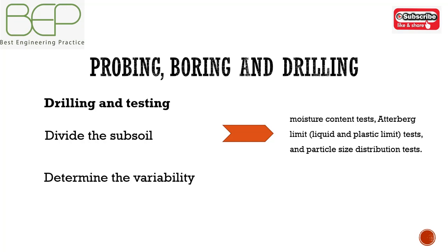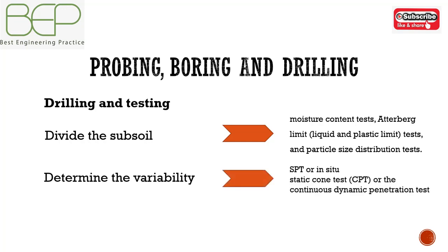The second objective is to determine the variability of each soil type or group. In addition, the results of in-situ tests such as SPT or in-situ vane tests are very useful for assessing variability. Even better, however, are tests which give a more or less continuous record with depth, such as the static cone test or the continuous dynamic penetration test.